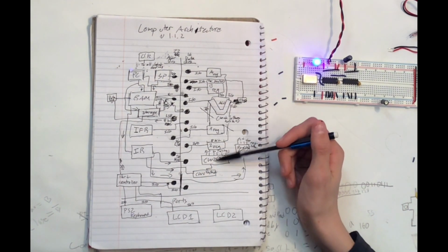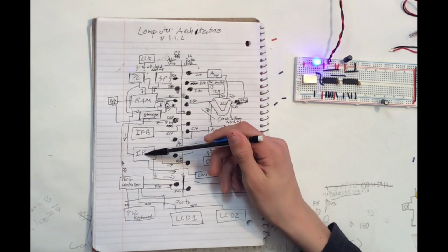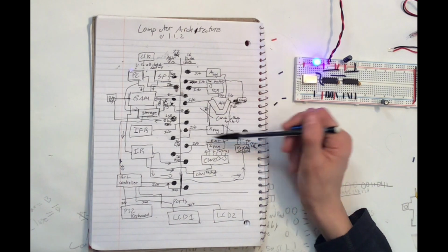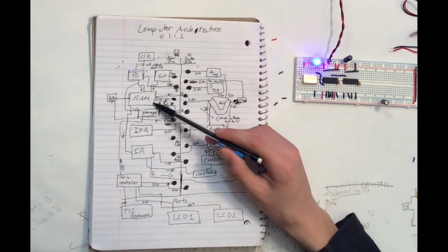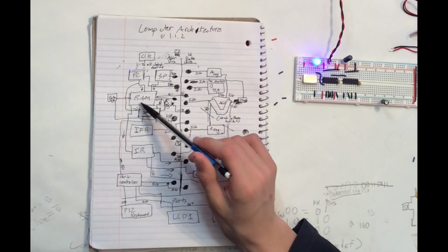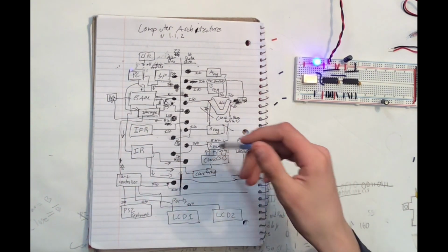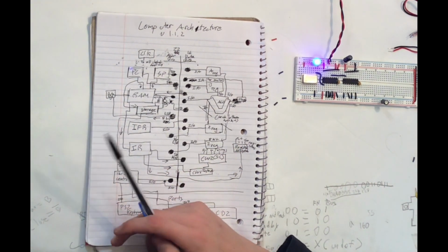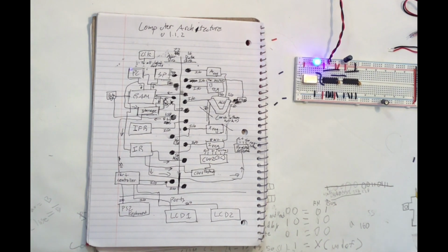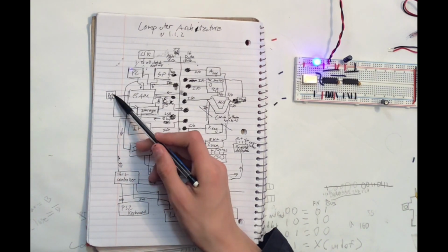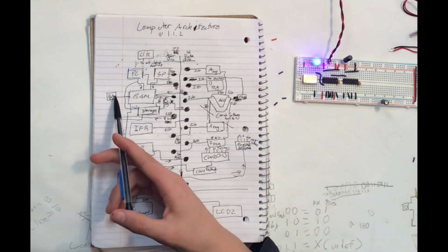Then we will have the instruction register I've talked about, the interrupt flagged register. This will connect to the main data bus. The RAM, storage, data segment. This is going to be used for the .data directives I talked about in the last video. It is a segment register, so that way I can put a value in that register and any address will just access from that plus the address. It's the top 8 bits of an address.